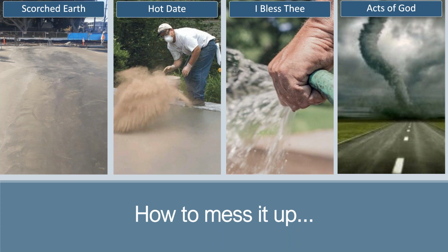What is a hot date? Well, I've been on a job site. The weather got cool. The truck was late showing up. It was a Friday afternoon. A guy literally had a date with his wife, and I came out of the trailer and he's throwing cement powder, feeding the chickens, to soak up the water so he can get on to start finishing it. I no longer have control of my water cement ratio. I've increased my risk of scaling. I've increased my risk of problems because all he had to do was wait. It's a one-way linear chemical reaction. If you give it time, it will get to where you need to go.